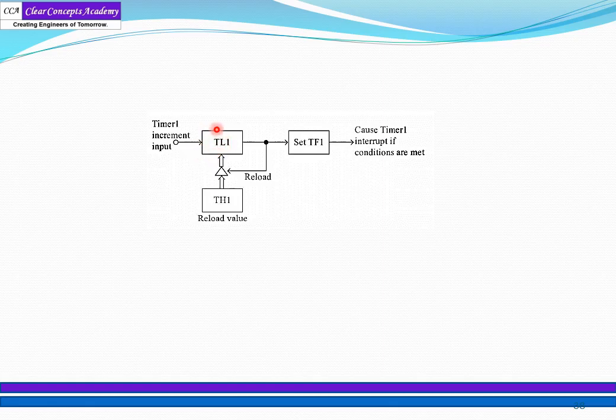TL1 will be incremented, and when it overflows, the value stored in TH1 will again be copied into TL1. So this is called the auto reload function.